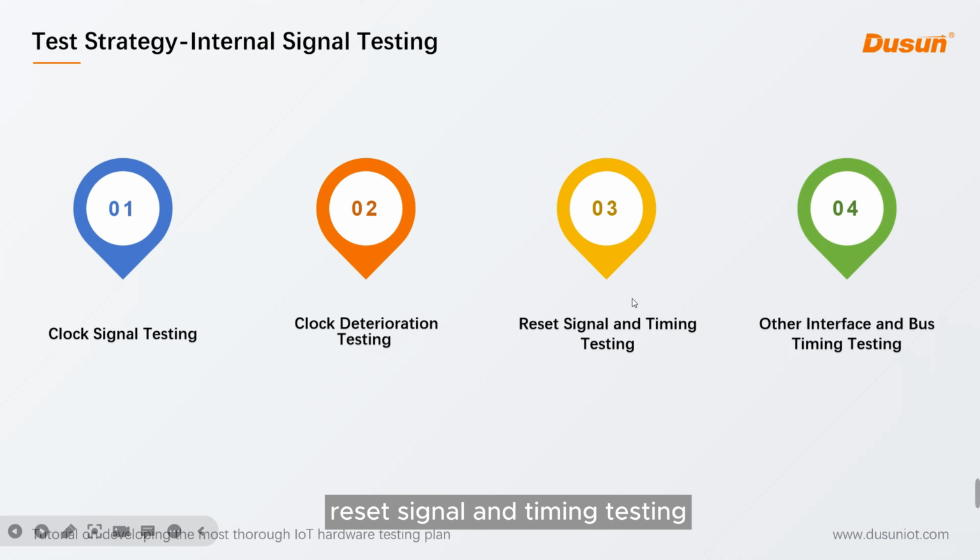Reset signal and timing testing. Measure the reset signal for each chip. Confirm the reset voltage level and effective reset time. And for reset signals with logic and timing requirements, measure the reset timing interval.